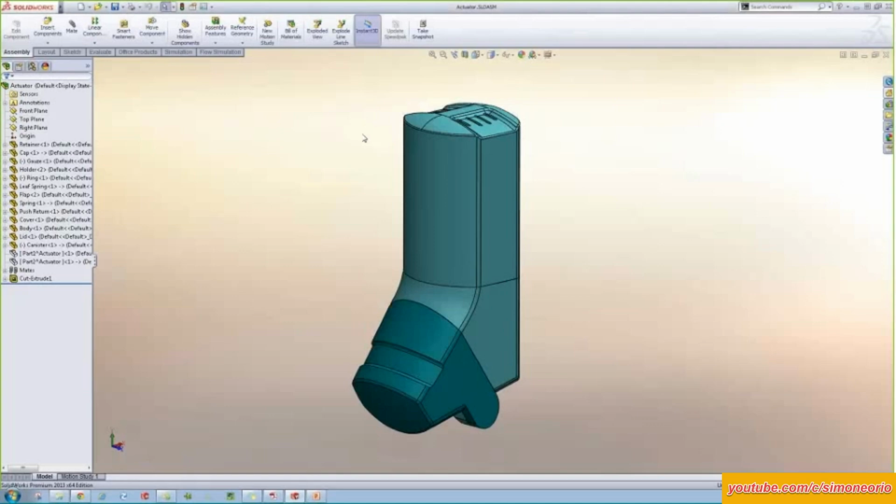So first up here is this inhaler model, okay? And I just want to show you what it would be like to use SolidWorks. If I hold my right mouse button down and just wiggle a bit, we get these mouse gestures. Some of these things might seem small, like small features, but when you add them all up, it really adds up to a nice user experience and be able to quickly get to where you want to get to.